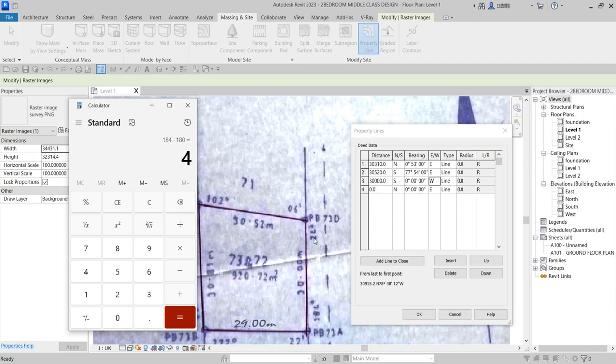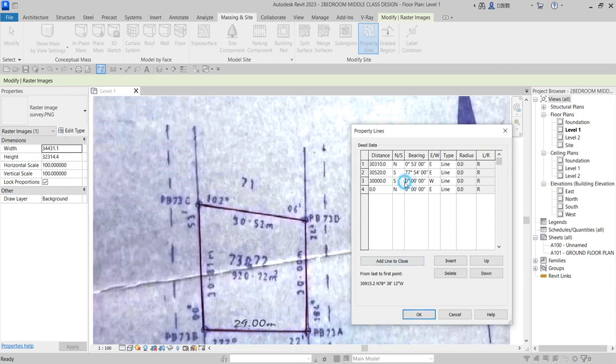So 4 degrees we take, since it has some minutes in it too, you take away 1. So you register 3 in this place, then you take away 1 degree. Remember 1 degree is equal to 60 minutes, so you are going to say 60 minus 24. It's going to be 36 minutes in this place. Since we have 24 minutes, we are going to say 36 minutes, and this one is going to west.